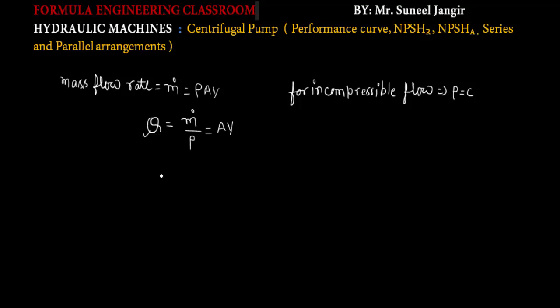Now the other parameter is the net head, which is defined as the change in Bernoulli head between the inlet and outlet of the pump. I am repeating again, the net head, let me say H, is the change in Bernoulli head between the inlet and outlet of the pump. So let's understand this first.